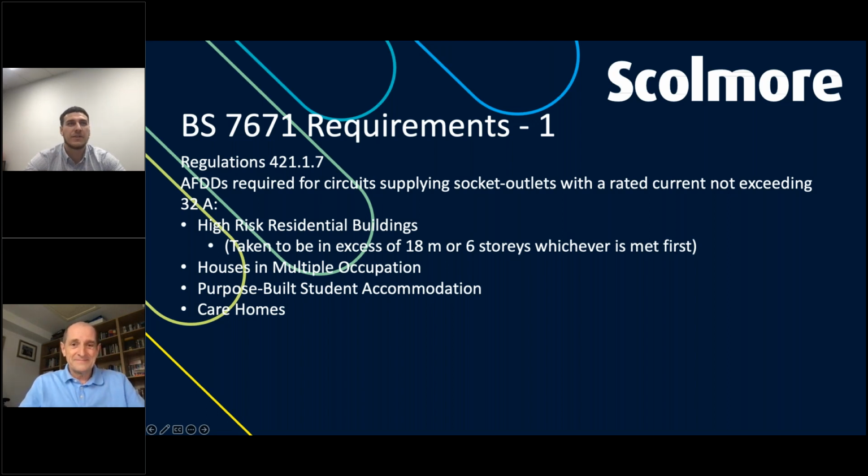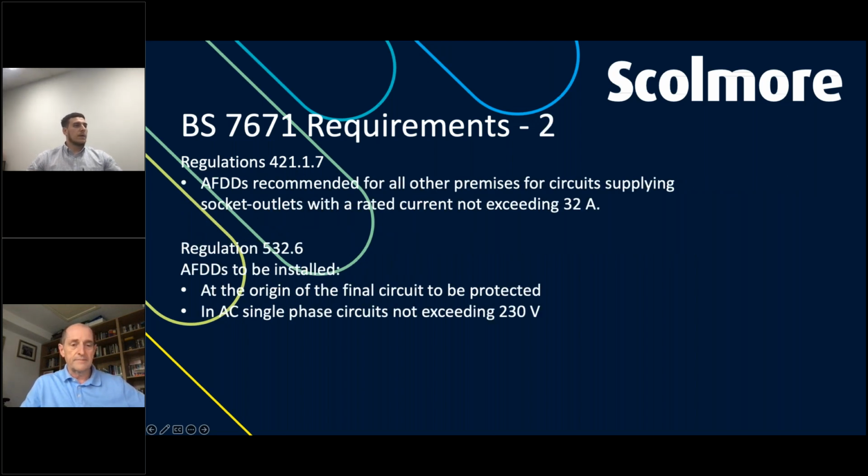We certainly do. So if they're competent, there's no way that the person using that system has any interaction with it other than pressing the button to turn it on and off, or maybe the pull cord. Now, when it comes to the socket outlets, like the regulations suggest, we can't control any of that. We don't know what people are going to be plugging into the system. I think it's a fair judgment when it comes to installing arc fault detection devices. Yeah, makes eminent good sense.